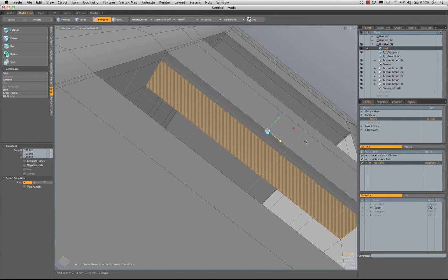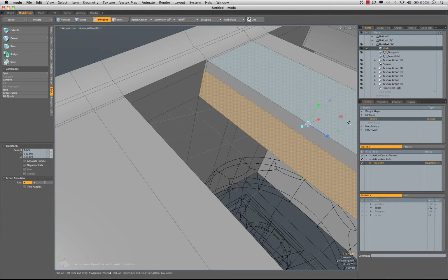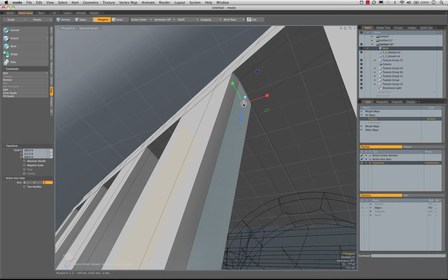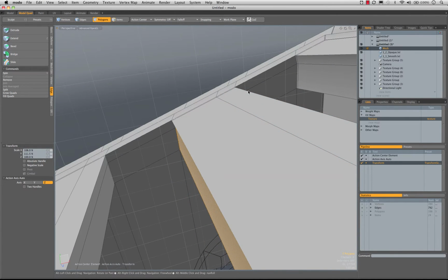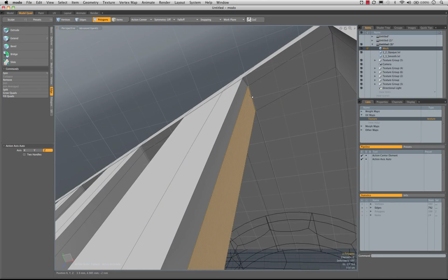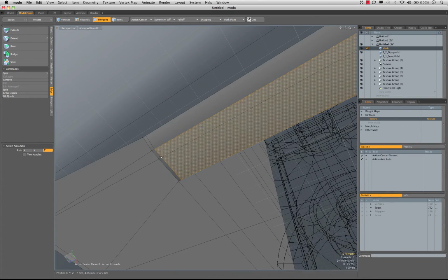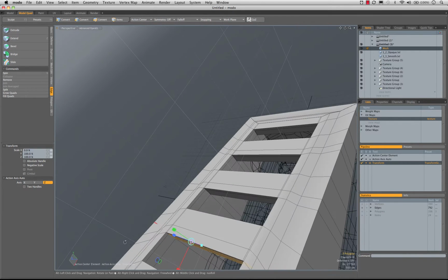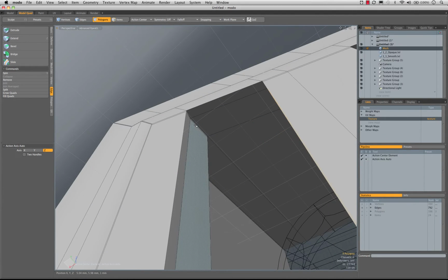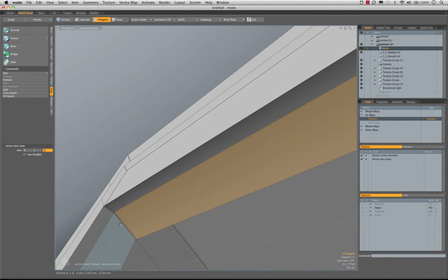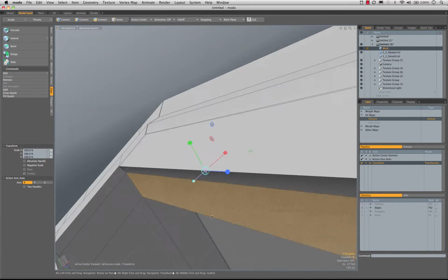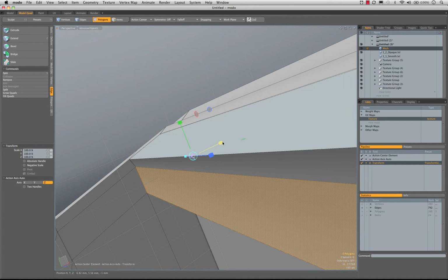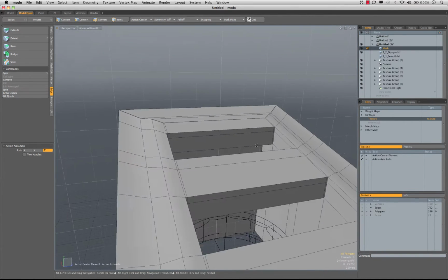Scale tool again. Make sure you drop your tool there before going on. And we're just about home free. I think we got one more left up here. Yep. Make sure you get that edge selected and don't click off the handles or else you'll be in trouble. All right, so there we go.